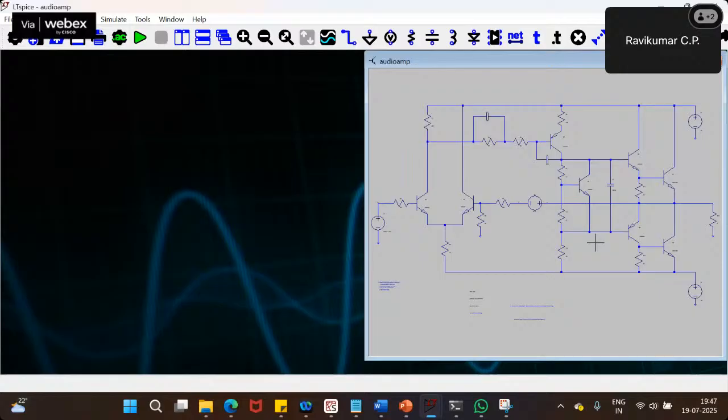They will all look sinusoidal. So the two examples that I gave, where one output was 7.0 and the other was 7 point something 4 or something like that, there the spec will come into play. If the spec says accept it, then you will pass the IC. Otherwise, you will fail the IC. Is that clear? Any questions there?